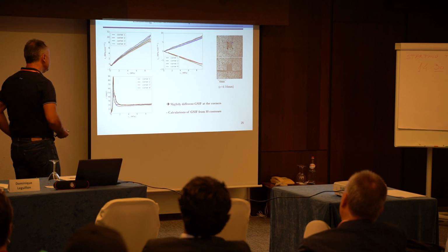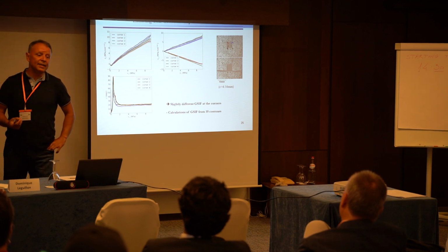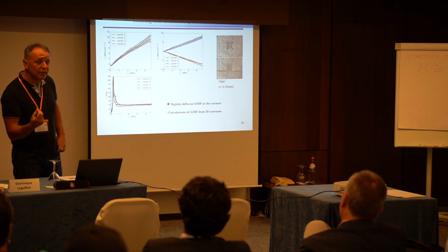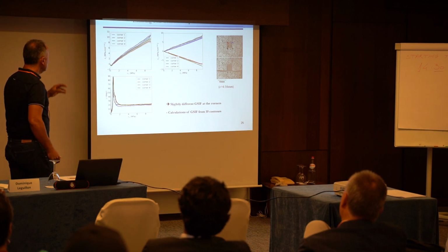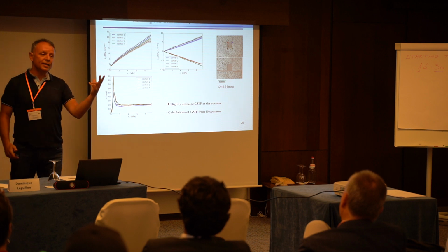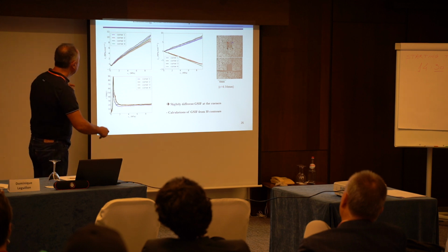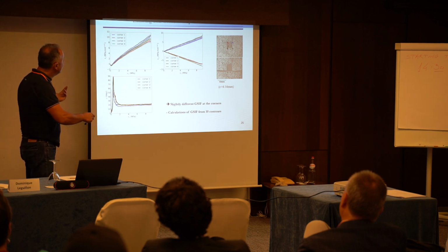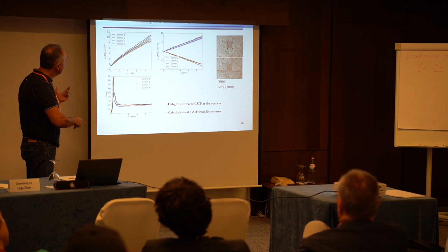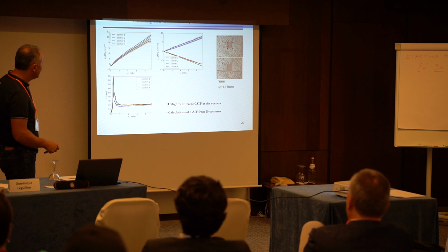So we are aware that performing a line integral with DIC calculations can come out with some scattering. And it would be preferable to have not a line integral but a surface integral in 2D. And that we are working on, that we are thinking on. But still, by performing repeated calculations of this line integral and taking the average, it is for us reasonably acceptable.